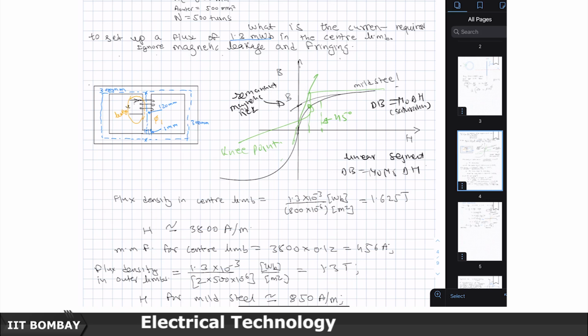any further increase in B, which typically will happen in an AC circuit, will not increase as per mu 0 mu r, but will only increase as mu 0 H. So, a ferrite core will suddenly start behaving as if it is an air core rather than a ferrite core. That is not what you want to do. You want your things to work in a linear sense here, and so you would try to use it up to the knee point, but not more than that.